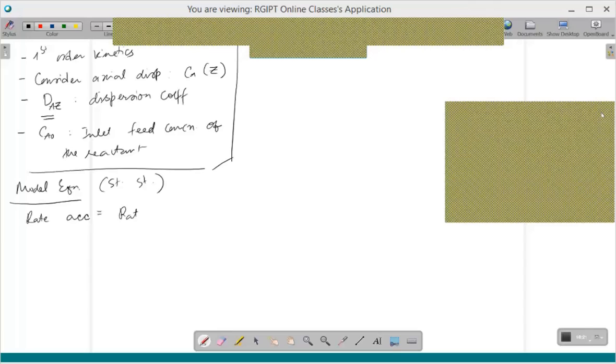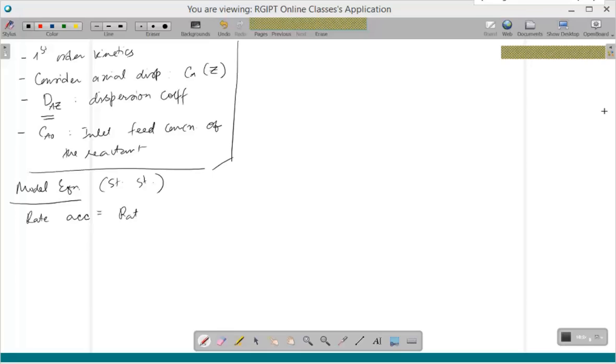Okay, Shalu. So I'll repeat what I meant by dispersion and diffusion. Dispersion is a more general term. Sometimes they use them interchangeably, but you have to remember one thing: flux equals minus D del C by del X. This is basically the constitutive equation of a phenomenon where a concentration gradient causes flux.